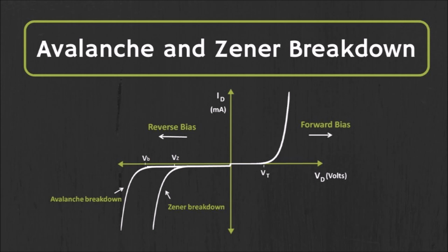The avalanche process occurs when carriers in the transition region are accelerated by the electric field to energies sufficient to create mobile or free electron-hole pairs via collisions with bound electrons. To me, that's not such a great definition.